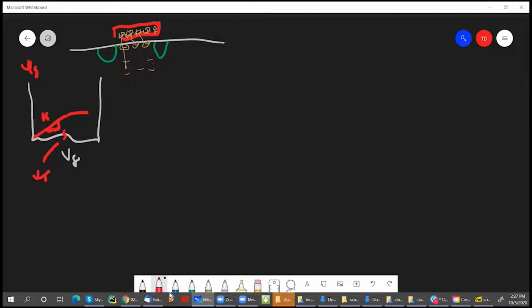But now we're talking about the mobile charge density, and let's draw that in blue here. That's like the density of mobile charge here in the channel per unit area. And how does that change as you change the gate voltage or increase it from 0? Well, I'll just tell you right now that in subthreshold, it increases exponentially. But on this linear scale, you can't even see it. We kind of scale the whole thing. So on the linear scale, all that 7 orders of magnitude of density increase just disappears. Now, as soon as you go above threshold, it stops being exponential and actually starts growing linearly. And the rate of change of that channel charge density is what? Cox.